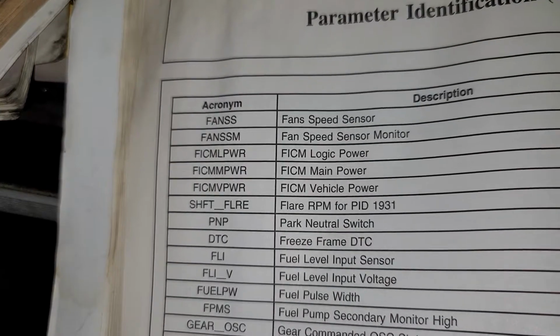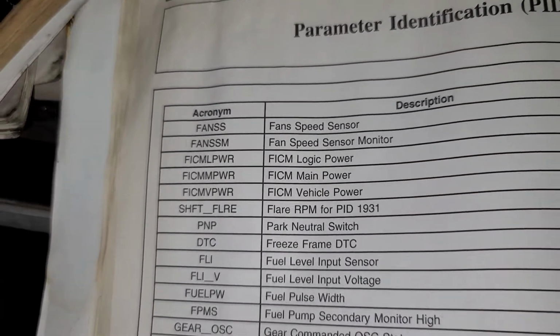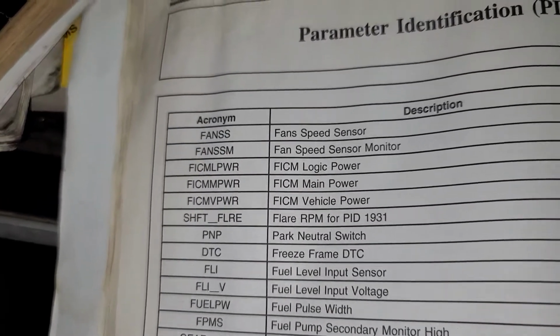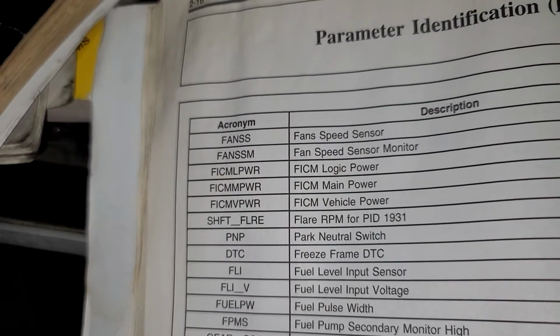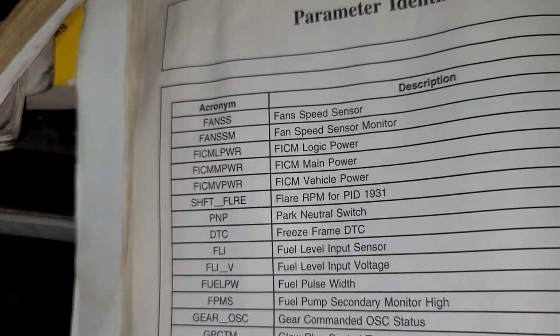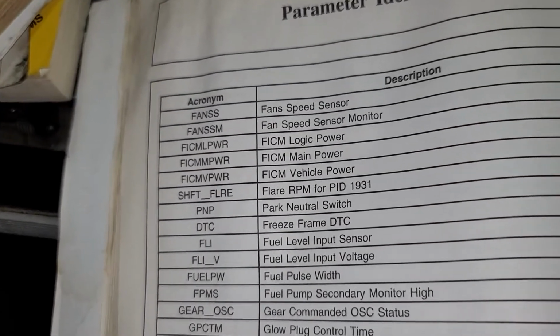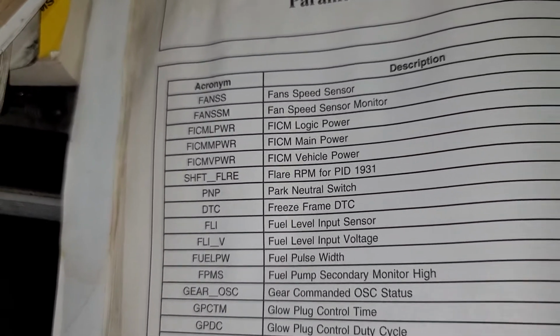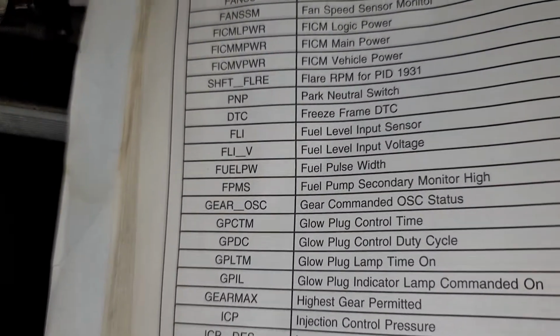If you see it dipping below 47 volts, it's starting to go. At 45 is what I think the book says. Sometimes it'll run at like 38, 36. It just starts to run rough, but sometimes it won't start at all. But that's a very important one.